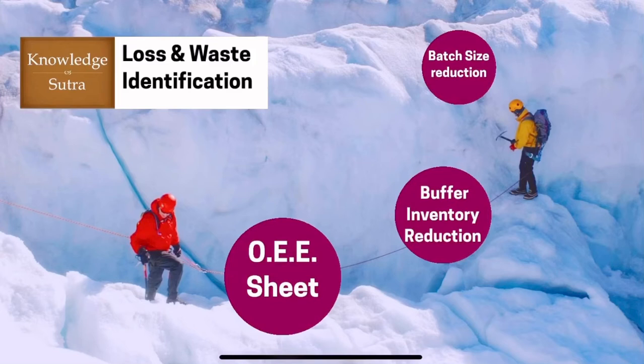So, we have come up with 3 ways by which you can identify these loss and waste in your manufacturing system. The first way is the O.E.E. sheet. The second way is by reducing the buffer inventory. And the third way is by reducing the batch size and thus reducing the mother of all waste, that is overproduction.